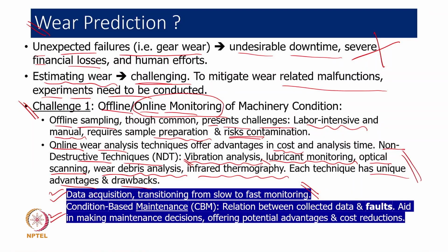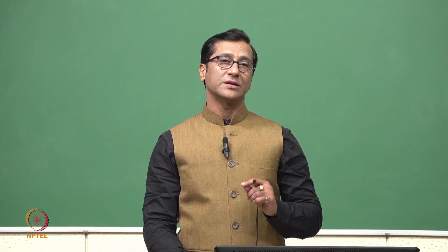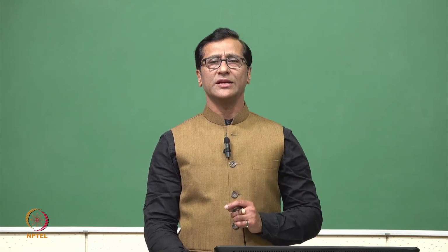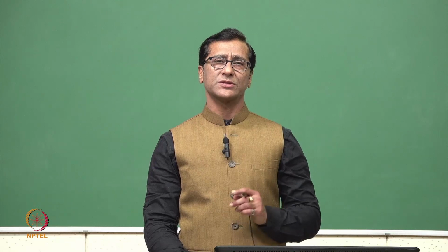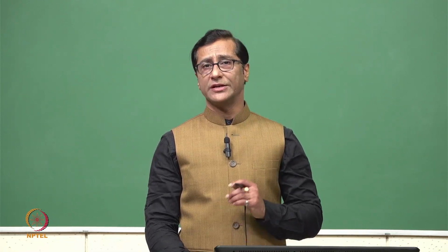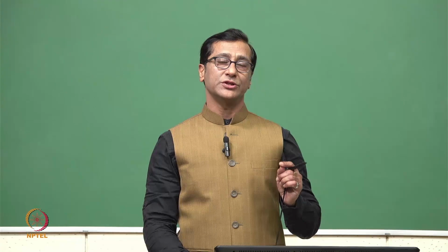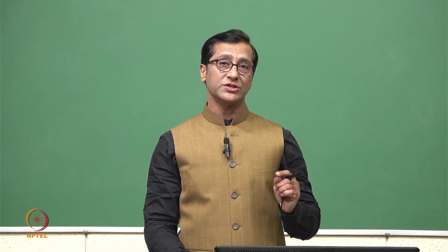Another technique which we have also covered to some extent is condition-based maintenance. We say we do not change the component till it reaches the stage where it is really moving out of the dimensions, or dimensional tolerances are moving out of the boundary, and then we require it. However, in this, major emphasis has been given to faults instead of failure. We say we diagnose a fault, not a failure. Failure is the final thing, where the component needs to be changed.